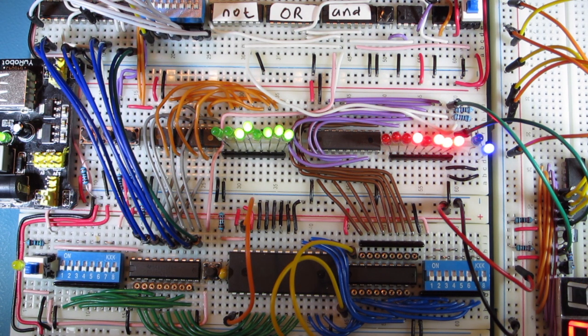We then have a couple of 74HC193s, I think, which are 4-bit counters. They're not just counters, they also have a parallel load function, which is why I selected those chips. And the reason for that is because if you're running a program and you perform a jump function or something like that, you need to change the value in the program counter. The only sensible way of doing that is with a parallel load.